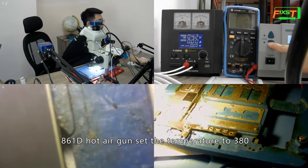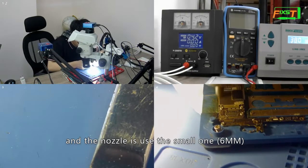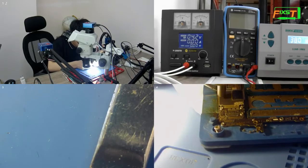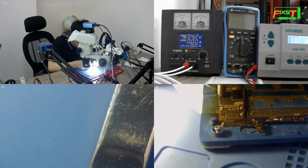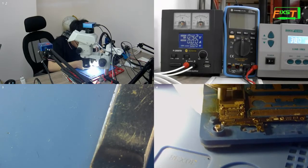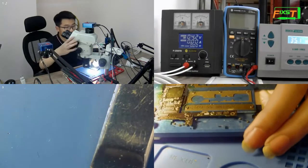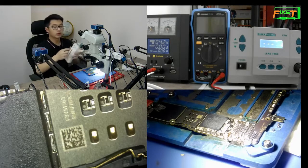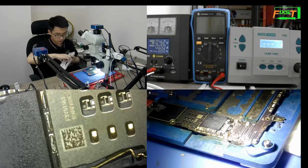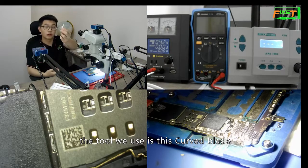A861D hot air gun, set the temperature to 380, and use the small nozzle. Use the tweezers to pry out the shell. To remove the CPU, first we need to clean the glue around it. The tool we use is this curved blade.